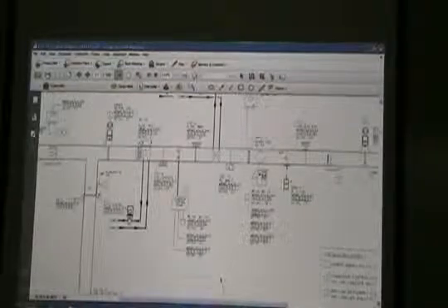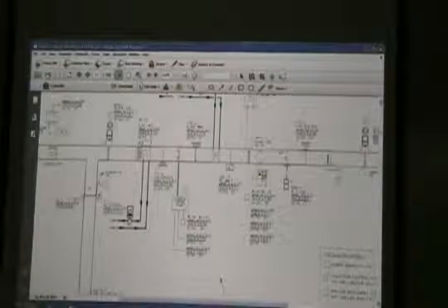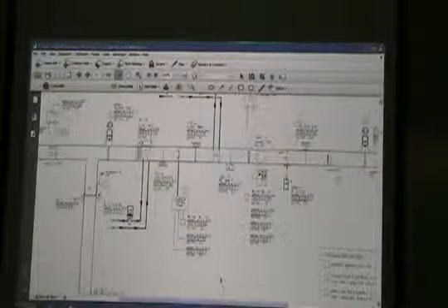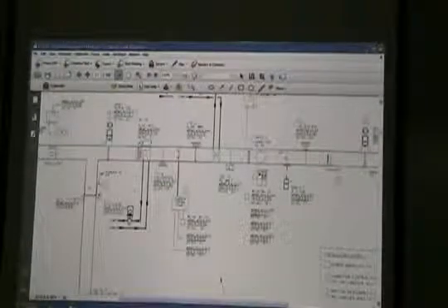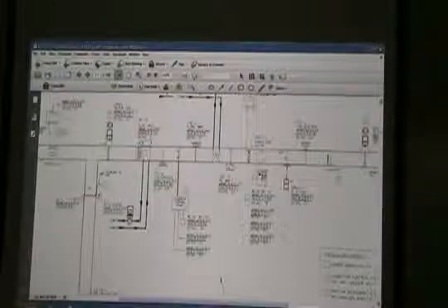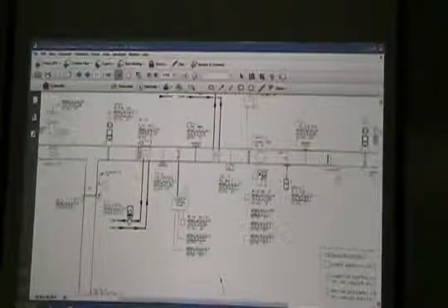So we've got to modulate. What happens is you close this damper, you open this damper, or mixed, we start closing, we start opening, so that by the time you get past that coil, you get a mixed air temperature of 55. So we might have 110 coming off the coil and 10 degrees going through the bypass, mixing to get 55.